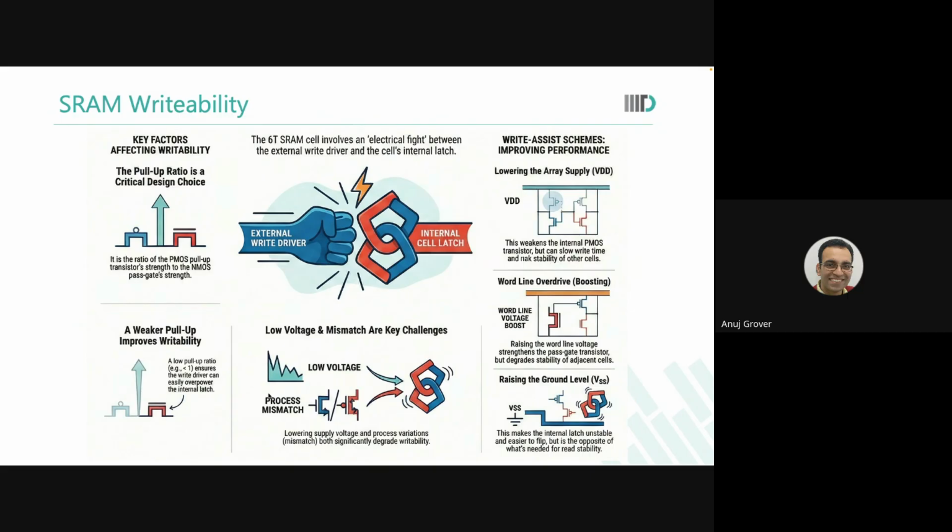Writing 0 is faster. Now, you remember we talked about bitline not being at VDD so that we can gain more stability. One very interesting and very important write assist scheme is negative bitline. Why is it more powerful than ground? Because bitlines again are shared only across 2 cells. Bitlines, even if they are shared for other cells, the pass gates are off. They do not impact the latches inside those cells.